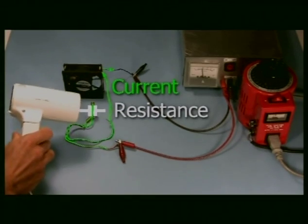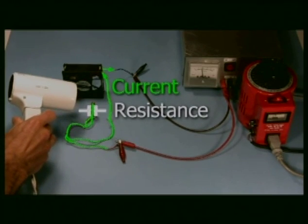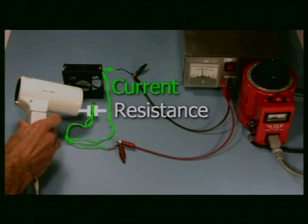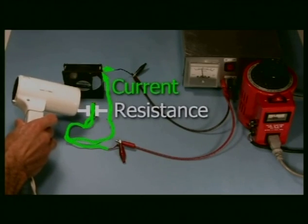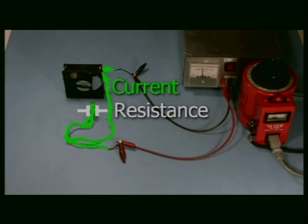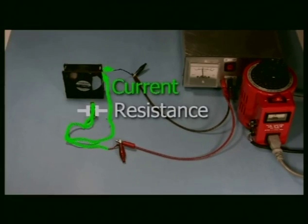Now I use this hairdryer to heat up the thermistor. That causes the thermistor's resistance to decrease. As it decreases, the current increases. And when the current's high enough, the fan starts spinning. Notice that the fan is blowing on the thermistor, making it cool off more quickly. Here I'm showing the airflow direction using this tissue paper. As the thermistor cools, its resistance increases, and that causes the current going through the fan to decrease. After a minute or so, the current is too low to keep the fan spinning, so it stops.